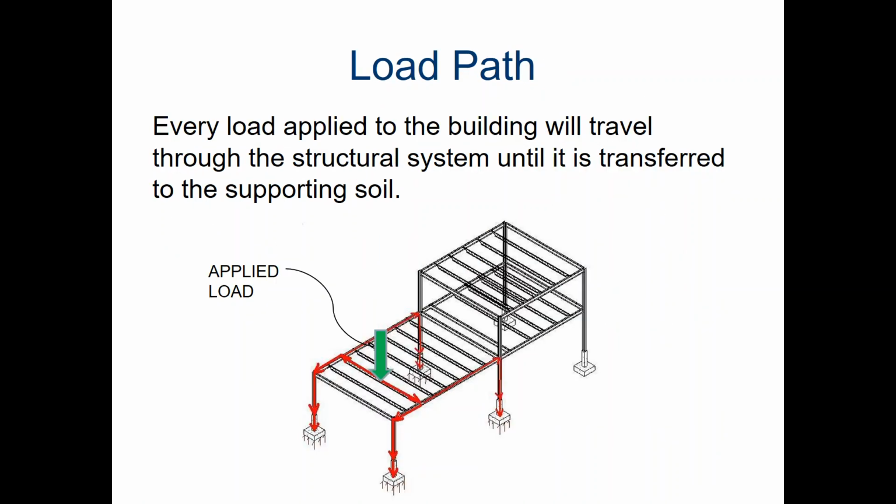So here's the Keystone Library, and now you can see in 3D what's happening with this load chasing. If we look at this green arrow, the loads placed on this girder by this green arrow are chased in both directions because it's centered. Let's go this direction here. It heads down to, I guess this might be better called a beam, to this girder over here. And then from that girder it gets chased down to this column, and then from the column to the footing.